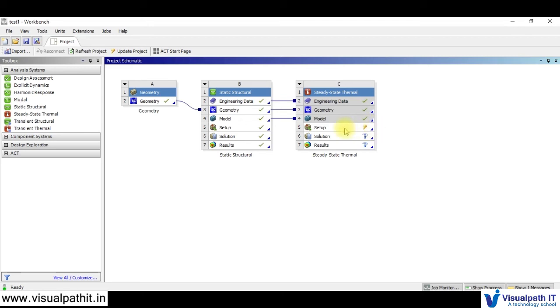So what is the update icon? Yes, there are some updates required. What it is showing is that I need to have boundary conditions applied to this model, and I need to solve the model. Once the model is solved, we will be getting ticks everywhere. Now it is a question mark because there is no data present for this. So there is some data available, or the deck is ready, but it needs an update. That is the objective of the update button. Now you can rename this by double clicking it here.